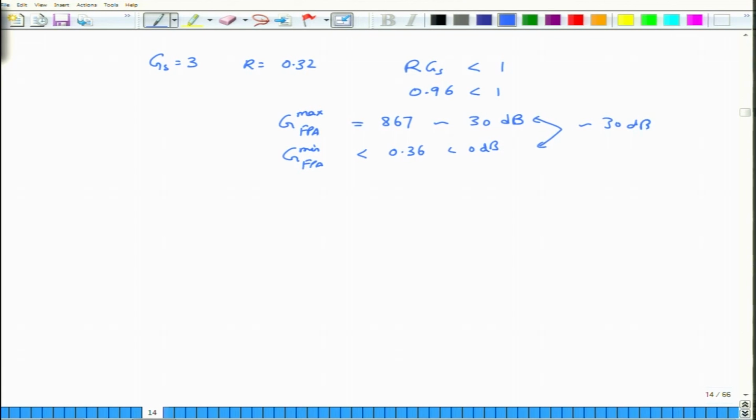If you have signals of two different frequencies, omega 1 and omega 2, and they happen to fall into this unfortunate situation, where this one is omega 1 and this one is omega 2, then the omega 1 channel will experience an extremely large gain, while the omega 2 channel will experience almost no gain, or in fact a loss.